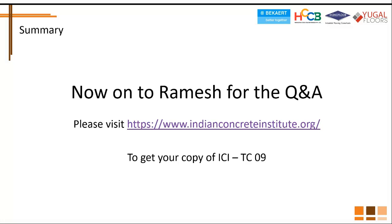Now even IRC, if you look at the latest version, says expansion joints are not needed in typical jointed pavement, except for, let's say, where you have a bridge abutment and a road intersection coming in and so on. Other than that, you don't need expansion joints for even roads as per the latest version of IRC. So I think we can stop hanging on to these historical practices and really see that if you remove expansion joints from your industrial floors, especially internal industrial floors, it would do a lot of good and improve the overall performance of the floor without really causing any other trouble.